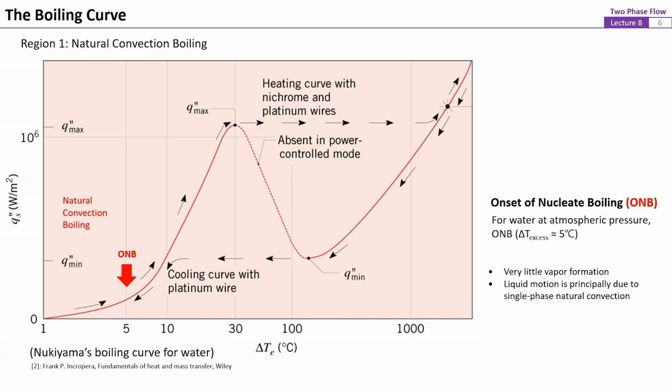In the beginning of the boiling process, there is almost no noticeable vapor bubble. Therefore, in this first stage of pool boiling, the fluid motion and the associated heat transfer is mainly due to the buoyancy effect, or simply called natural convection.